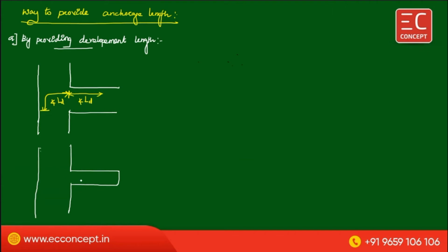And here we have to provide the anchorage length in such a way that you start from the face of the support here, it comes and goes something like that, and from here to here it goes. This is the anchorage length that you have to provide within the support. This is the anchorage length you have to provide on the beam, and this value also should not be less than LD, and this value also should not be less than LD. This is for small cantilever.